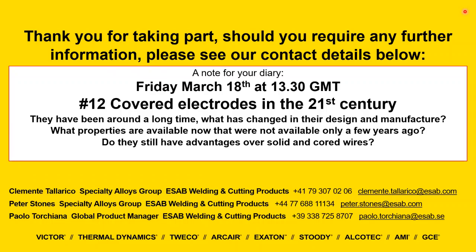Usually the recommendation is to use at least one part of new flux out of 3 parts of the recycled. So 1/3 more or less. And about redrying, usually it's not mandatory, because if the flux and the box, the bucket are still unopened and new, it means that the flux has reached the customer warehouse in the proper condition as produced. So usually it's not mandatory, but for tough applications, in many cases it is still recommended, because it will improve the weld, the slag release, the bead shape, and so on. I understand it might take some time to redry it, and it's a bit of an expensive exercise, of course, but it might lead to savings of some man hours later on during the production, not because of repairs, but maybe some less cleaning activities.